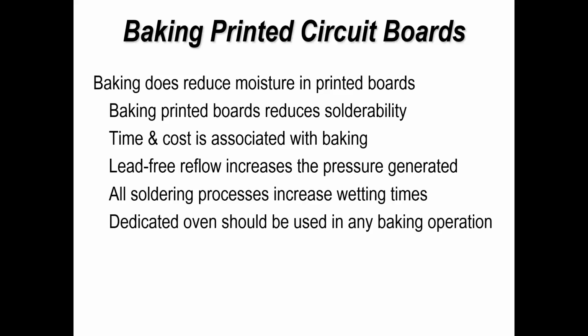If you compare tin lead assembly with lead-free assembly, it's obvious that lead-free is higher temperature, so delamination and distortion of packages would be more prevalent. But if you were looking at low temperature soldering, as a lot of companies, myself included, have been looking at over the last couple of years, that's going to be another benefit for our process in terms of moisture content in packages, warpage of packages, and damage. So again, that's a benefit to us.